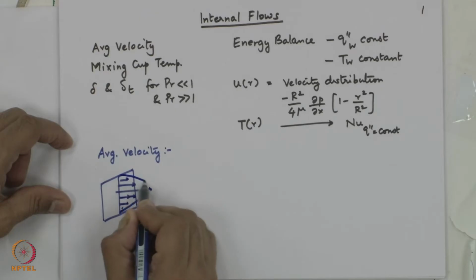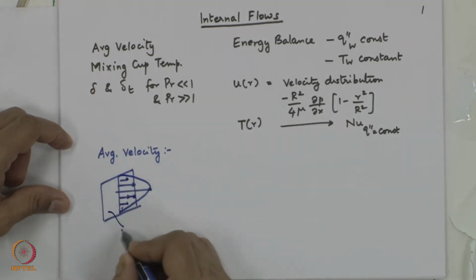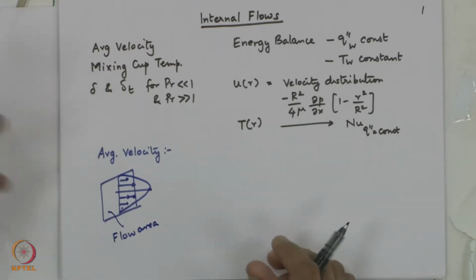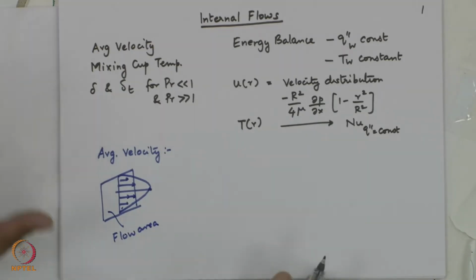You would have a velocity profile which is something like this, if this is the flow area. It will come out to be like a paraboloid of revolution, a 3-dimensional parabola or a parabola which is rotated. So, you will see a bullet head shaped structure typical of laminar flows.